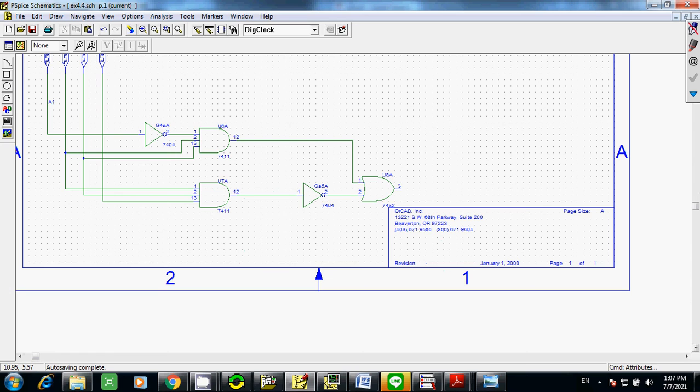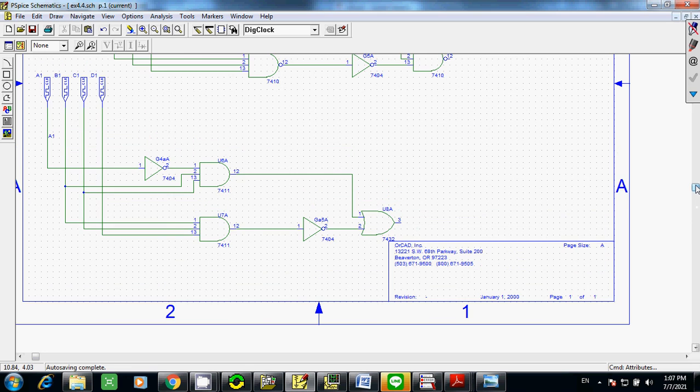And if you want to compare to your original circuit, since you already put A prime, B, C, and you AND, right? You don't need NAND gates. You just simply use the straight AND gates. This also is an AND gate, and instead of using a NAND as OR, you would simply use the 2 input OR gate.